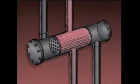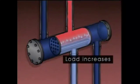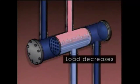Inside the condenser, heat is transferred from the hot vapor to the cooling water that flows through tubes inside the condenser. The condensation process causes the vapor to change into a liquid. If the flow rate or the temperature of the vapor increases, more heat has to be removed from it. Under these circumstances, the cooling water system must be able to supply more water to absorb more heat, so the load on the system increases. If the flow rate or the temperature of the vapor decreases, less heat has to be removed, so the cooling water system doesn't need to supply as much water. In this case, the load on the cooling water system decreases.